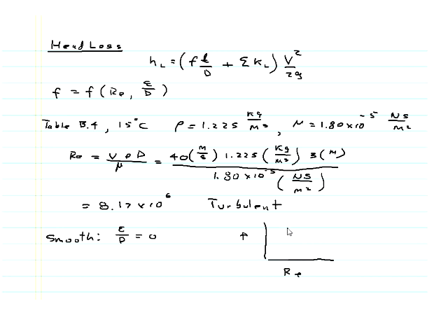For smooth pipes out in the turbulent regime, the curve looks something like that. If we go in at a Reynolds number of 8 times 10 to the 6th, we'll come up with a friction factor of about 0.0083. And again, it's not too important to be very accurate with this. Two significant places is enough.